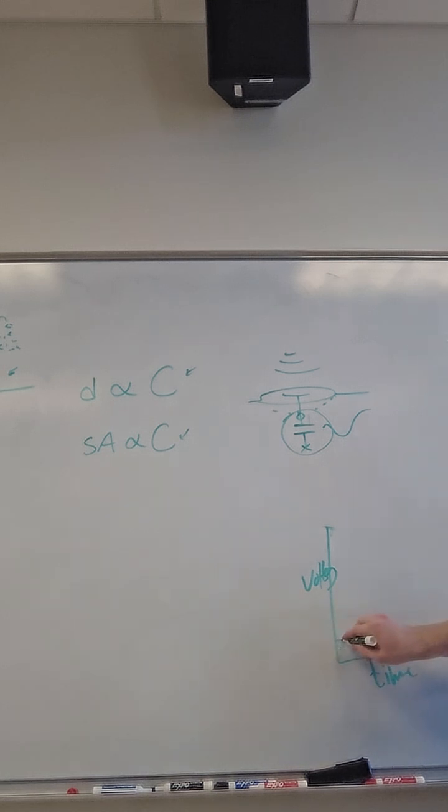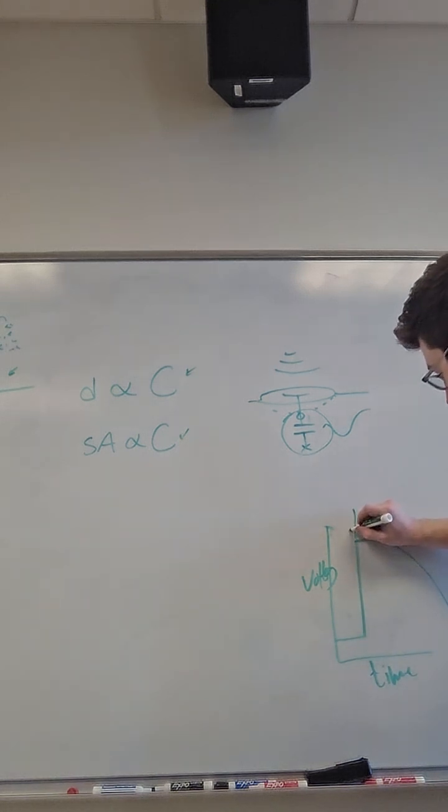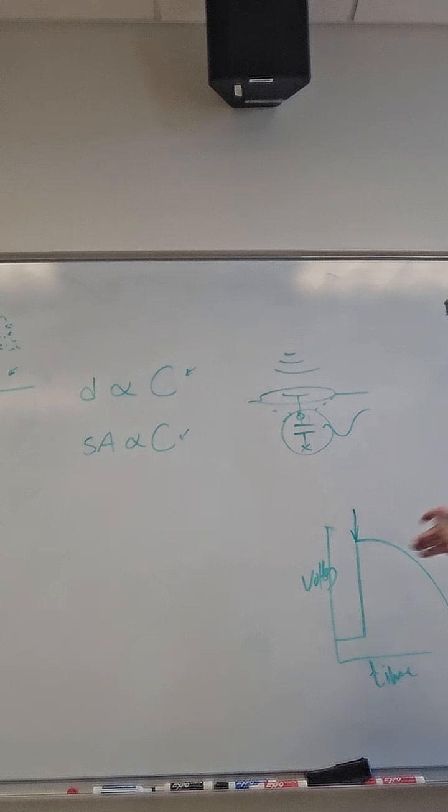If we suddenly charge the capacitor, and then take away the thing that's charging it, for example, if we charged it with a battery and then just took away the battery and let it discharge, it would slowly discharge kind of like this, right? The voltage would kind of curve, and then it would maybe level out like so over time. So what we could do is charge it, turn on the source with a transistor, and then wait some number of milliseconds later. Boom, check in again. What voltage level are we at?